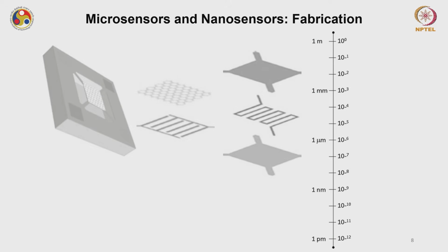Usually in the laboratory, people test them by dropping some microliters of the material if it is nano dispersed. Otherwise there are physical and chemical vapor deposition techniques where you can actually control the thickness of the deposited film. And for various printing technologies, the suspensions of these liquids, prepared by various methods, maybe hydrothermal, sol gel or any other method, are used for fabrication of this receptor film.